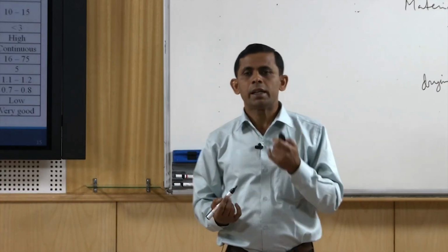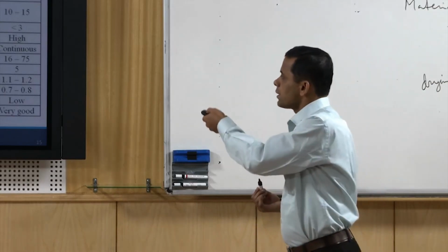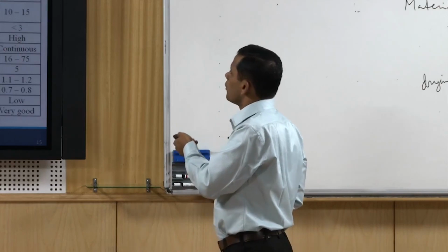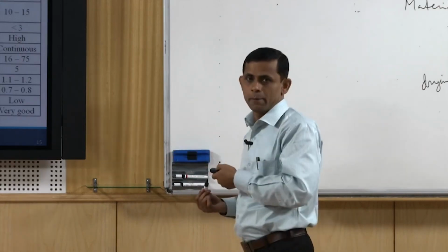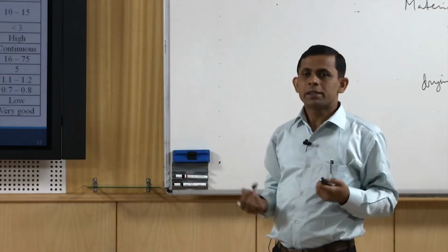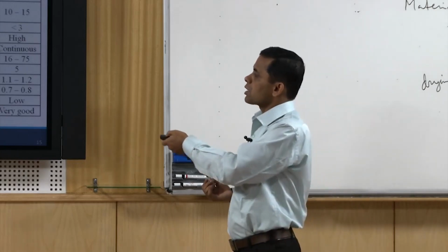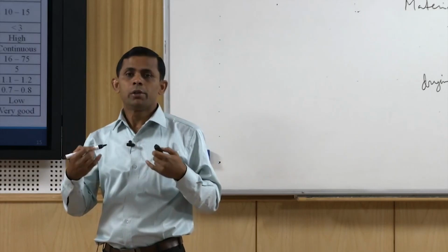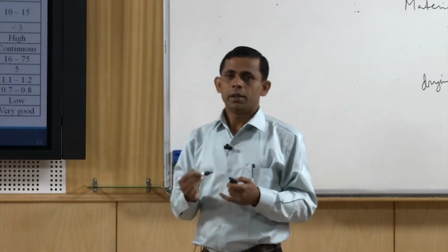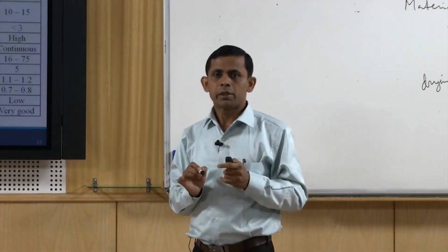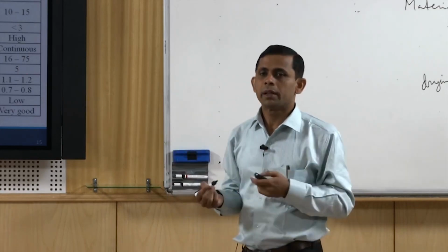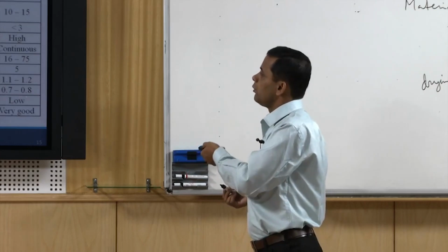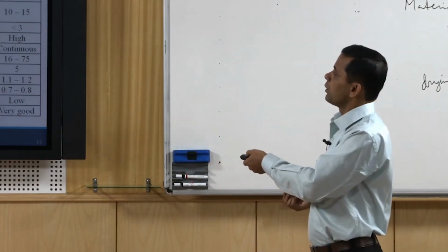We see it is very high for the screw press and very low in the case of the pellet mill. So, the bigger the capacity, the lower the specific energy consumption, but the limitation is where we will be using the briquettes. If everything is systematic and we have good demand for briquettes, we can go for the pellet machines where the energy requirement will be less, otherwise we may opt for these 2.